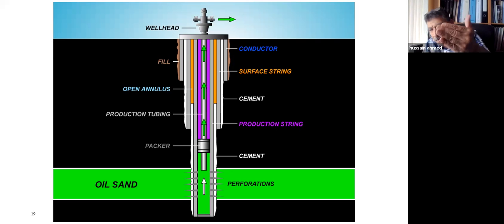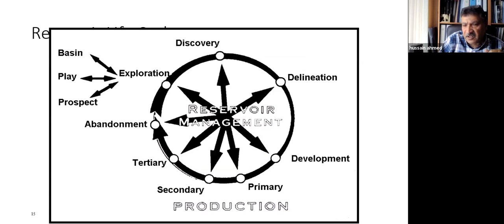And also there are barriers on the surface: the wellhead, the Christmas tree, the flow line, the choke, the gauges, the annulus between production tubing and the production casing, the pressure build up, the reading of the pressure in the casing. Of course, casing should reach zero pressure, but with integrity failure, it will reach some pressure. How to release it as well. So on integrity, I will talk very much about factors affecting integrity.